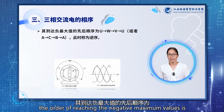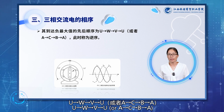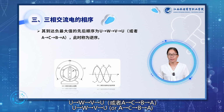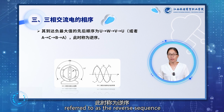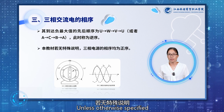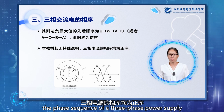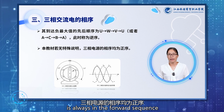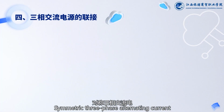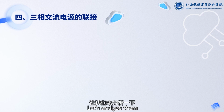Conversely, the order of reaching the negative maximum values is U to W to V to U, or A to C to B to A, referred to as the reverse sequence. Unless otherwise specified, the phase sequence of a three-phase power supply is always the forward sequence. Symmetric three-phase alternating current possesses certain characteristics. Let's analyze them.